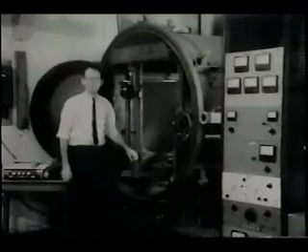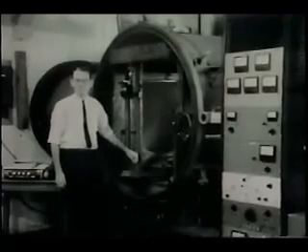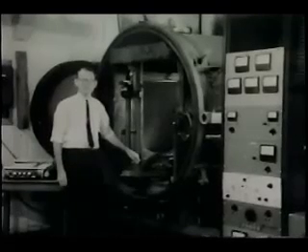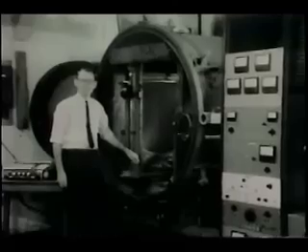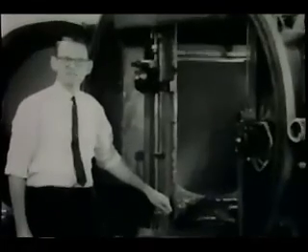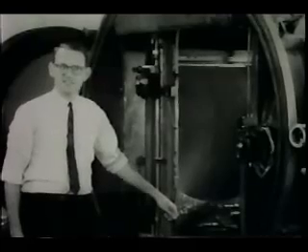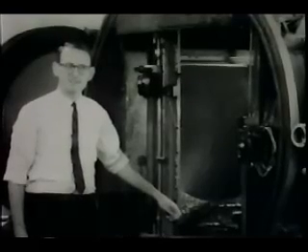We use this bigger wind tunnel for quantitative studies of rarefied gas flows. Right now, we're going to take a closer look at the bow shock wave in front of a model which is in continuum supersonic flow. While we're at it, we'll learn something about heat transfer to bodies in rarefied flow. The model is a flat bar of aluminum. It's mounted on a thin-walled stainless steel tube to reduce heat conduction between the model and the wind tunnel shell.